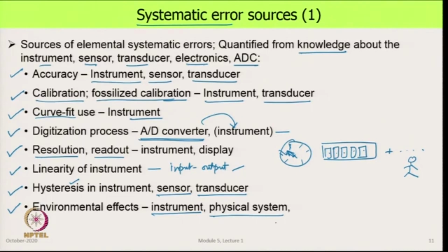And what I mean is that if you are studying something, say flow of water in a pipe or air in a duct. So, this is a pipe, say, and something is flowing through this. We want to do a pressure drop calculation and connect it with the viscosity, velocity. We may need the value of viscosity, we may need the value of density. Both of these are temperature dependent.